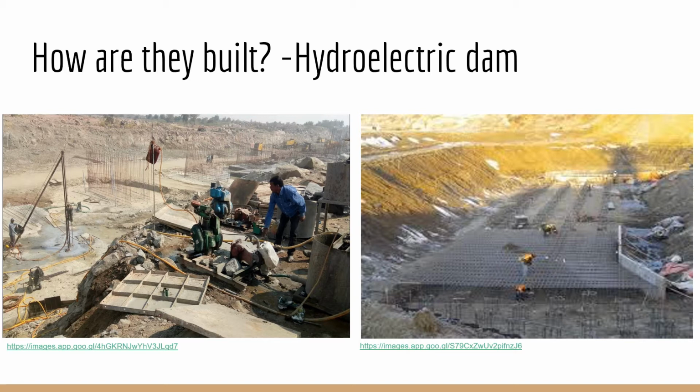For concrete dams, they can be molded before placement or poured and compacted with rollers. Embankment dams, also known as earthen dams, are built up in layers of various compositions of soil, sand, clay, or rock, using the most impervious materials to form a core and placing more permeable substances on the upstream and downstream sides. Once the dam is completed, a protective waterproof layer is added to its upstream face. This layer is added to both concrete and earthen dams.